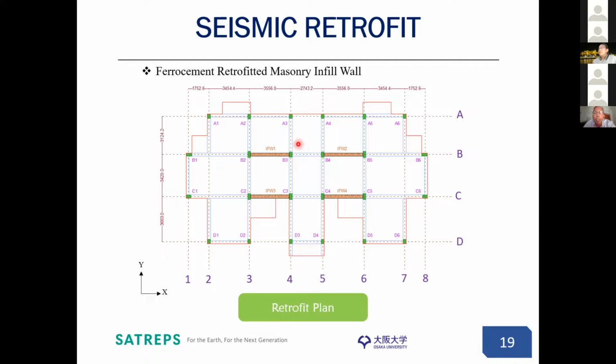However, we couldn't find 2 spots to retrofit that would keep a balance in that direction. Because this is the staircase, we cannot retrofit this part, because if we install a wall here, the stair will be completely useless. So this 2 frame is not an option. That's why we needed to install 4 to keep the structural balance, and it will do some additional retrofitting to the structure, which might not be required.